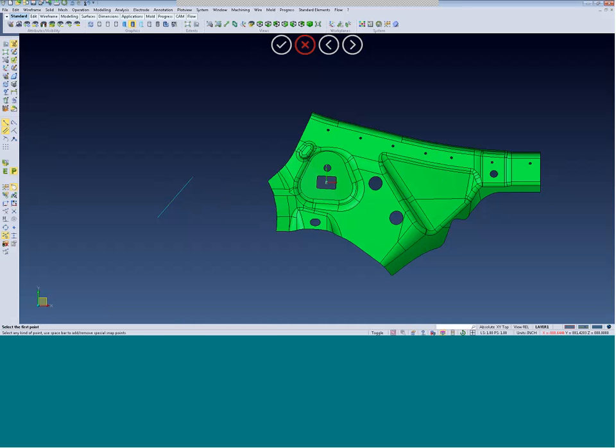Now let's say I want to start another line that's 1 inch to the left of this endpoint. You can see that as I hover over this endpoint, there's the insert XYZ offset box that pops up. So all I have to do is enter the coordinate relative to this point. So if I want to start 1 inch to the left, I'm going to go ahead and type in a -1, 0, 0. I'll go ahead and hit enter, and VISI will start a new point at that location. I'll just go ahead and place that.